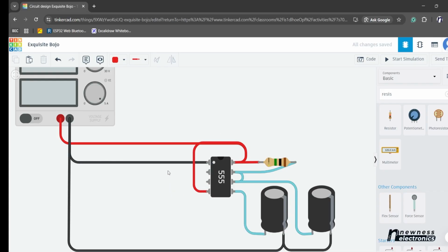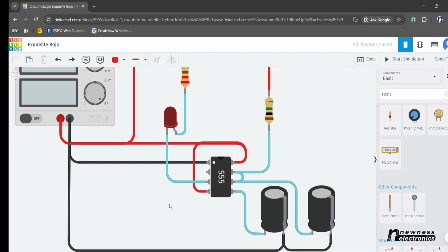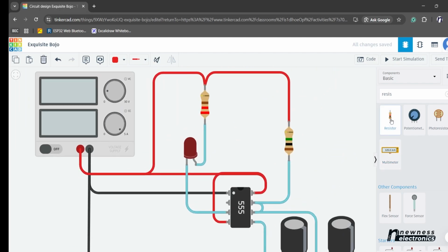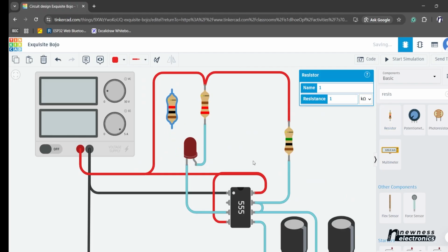Actually, you know what, we didn't connect pin 2 to anything and yet it worked. That is not right. Before we go ahead, in a real life scenario, you may experience issues. So normally you should connect pin 2 via a resistor to the positive power line.